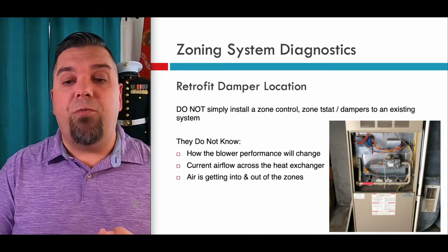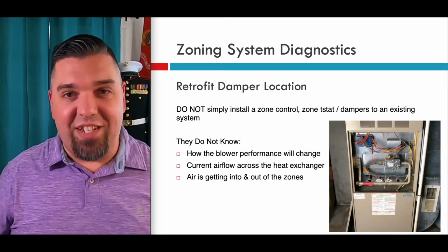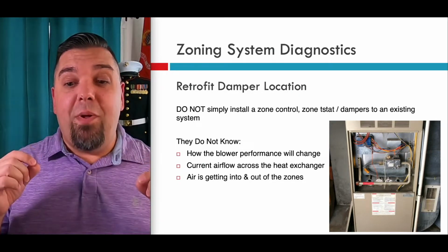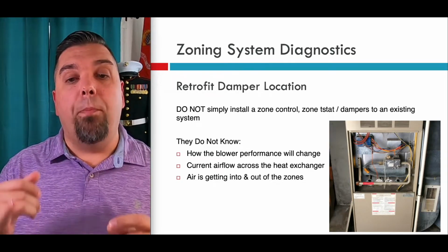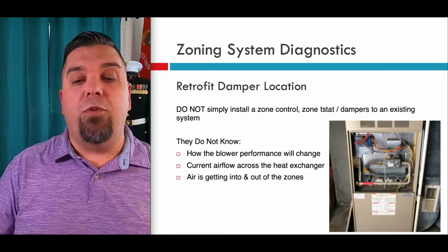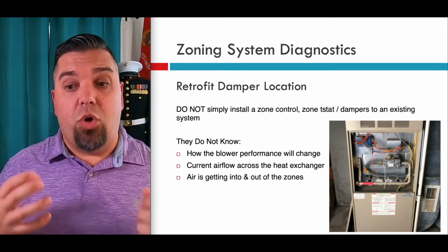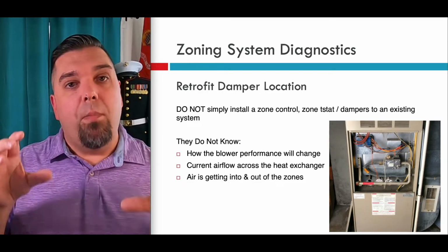When you retrofit a damper, you can't just willy-nilly throw one in the duct system. It's really, really important before you do that. You need to know the blower performance and how it's going to change. You need to measure the airflow across the heat exchanger. So in the actual operating season, as it's operating, measure the volume of air.